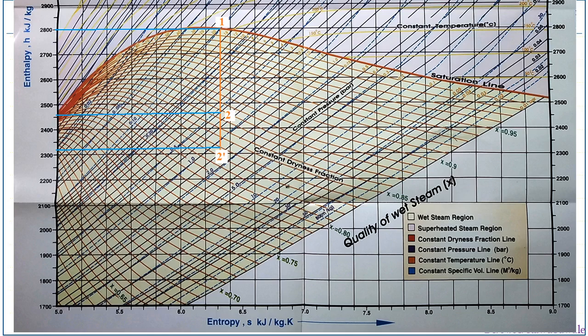So what is given in the problem is, the steam is expanded from 20 bar and dry saturated. So this pressure is shown here, 20 bar, and dry saturation. This curve is the dry saturation curve. So this point is located here, point 1. Steam is expanded from point 1 directly to the pressure of 1.2 bar. So here this curve is representing 1 bar pressure, and this is representing 1.5. So 1.2 bar is between 1.5 and 1 bar.